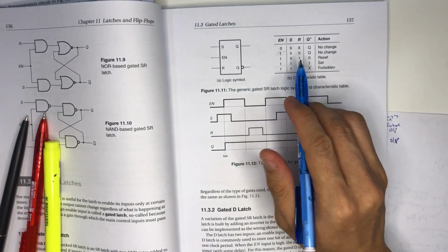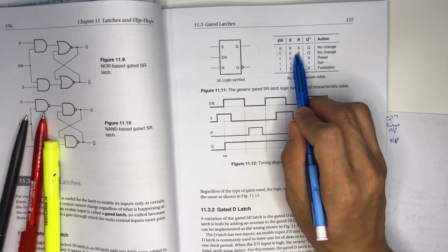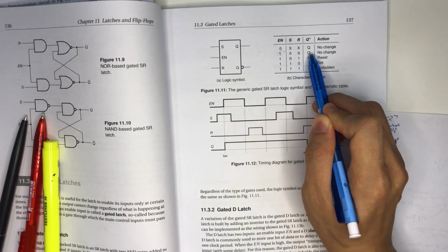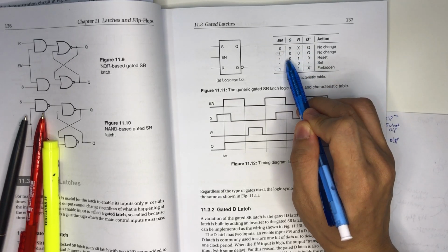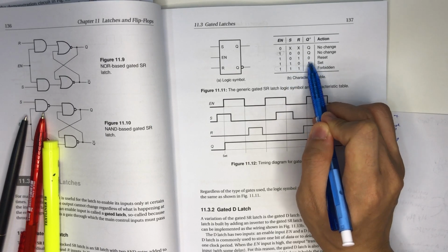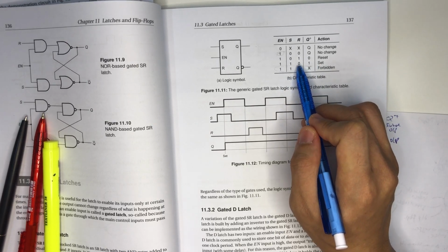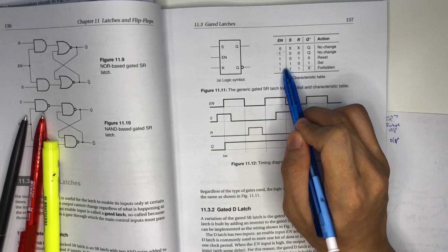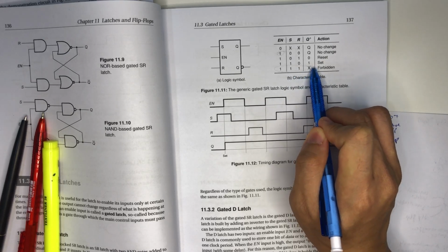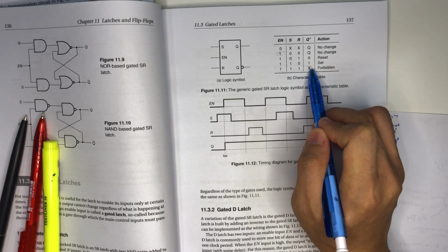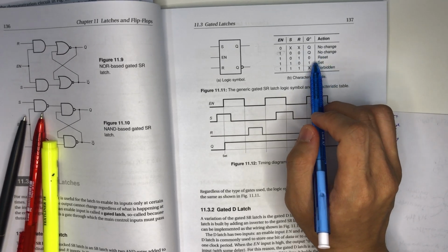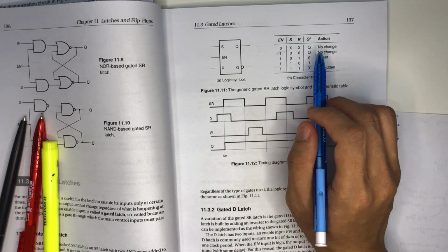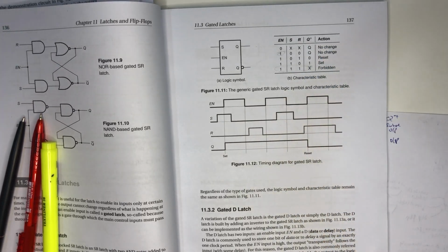Then later, when we have 0 and 1, what happens? It will undergo reset, meaning reset to 0. Then the next, when you have S as 1, you will set back to 1. Similarly to an ungated latch, if you have both S and R as 1, then your output will be forbidden. Similarly, your output will be low. You cannot have both outputs Q and Q bar low, right? They should be the reciprocal of one another. So that's why it's wrong. This is called the forbidden state.